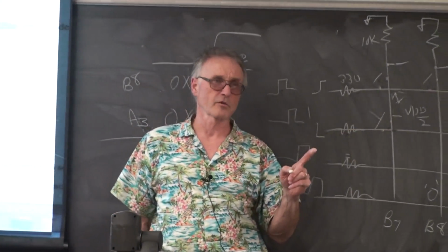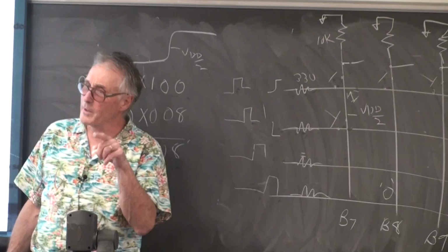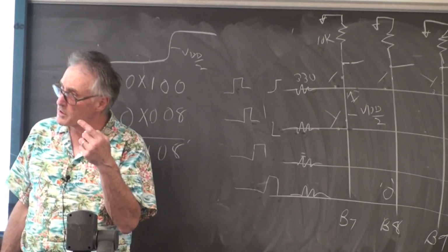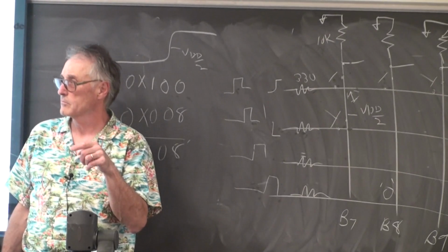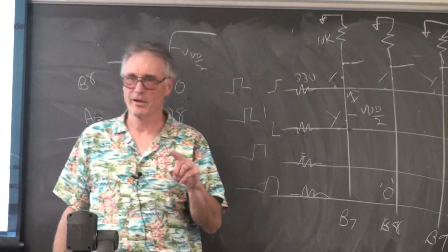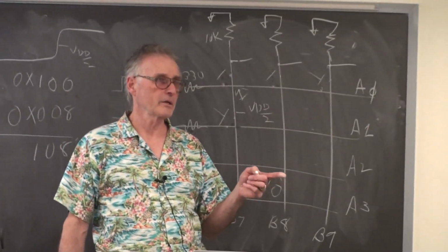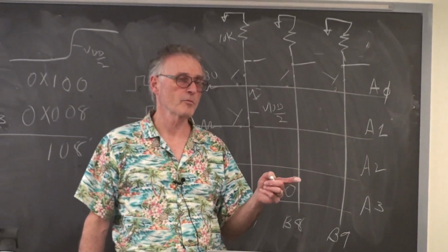You don't know how the port's going to read it. It's either going to read it as a very weak 1 or a very strong 0. So it may or may not reject that particular error condition without further processing.